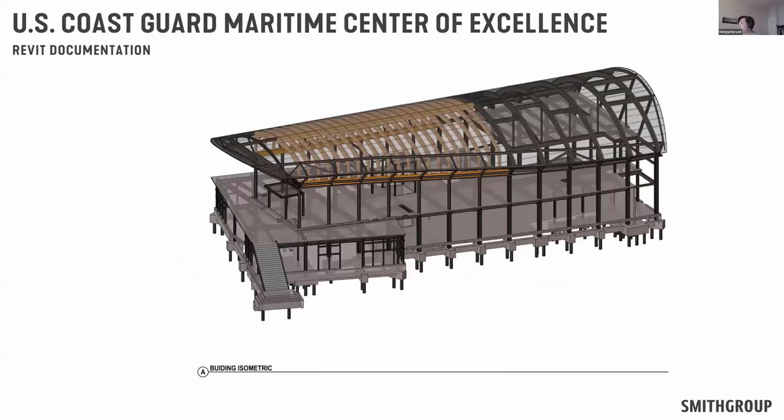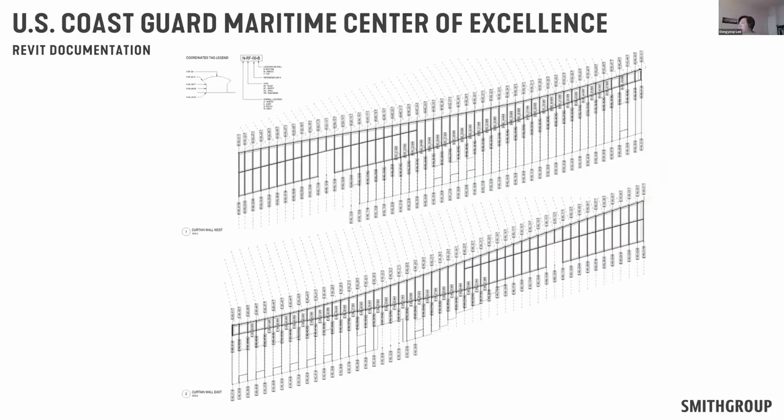The structural engineer successfully created frames based on the roof surface we provided. However, we had to model exposed glulam beams for the documentation. Those beams were transferred from Grasshopper to Revit automatically using the same method shown in the previous video. The work points were critical to describe the geometry of the panels. All these work points were also automatically transferred from Grasshopper to Revit. Additionally, tagging was automated by running a Dynamo Player script.